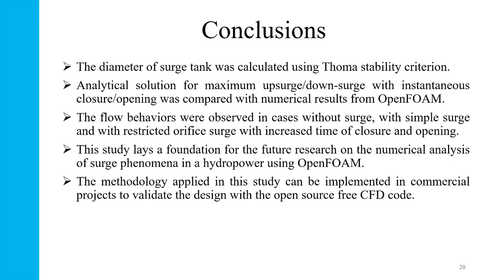Then, numerical simulations were performed in OpenFOAM by increasing the time of opening to 30 seconds and time of closure to 6 seconds. The increased time of closure and opening showed reduced values of mass oscillations, observed height, and pressure fluctuations. Also, the cases without surge, with simple surge, and with restricted orifice surge were compared.